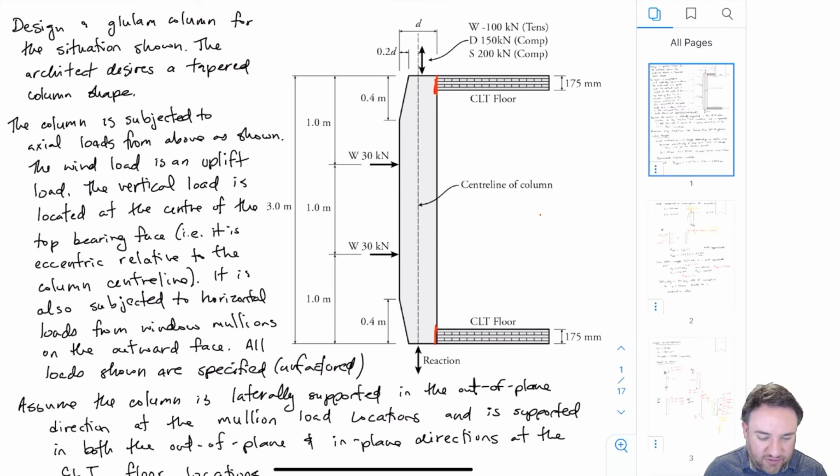They're both 175 wide, like 175 long, sorry. And the beam itself is 175 wide, right? That's the in and out of plane thickness of the beam. So the bearing area is 175 by 175. Did you remember that beam is a 175 by 304?